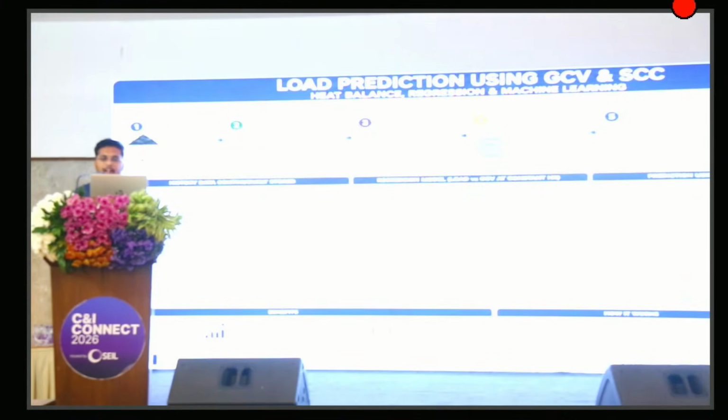So after getting the exact online furnace GCV, using constant heat rate, we calculate specific coal consumption. After knowing the specific coal consumption, we'll know the coal flow. Those relationships are used for the load prediction system. Likewise, a regression model was developed between load and GCV. By knowing the coal quality at GCV, we can easily predict the load.